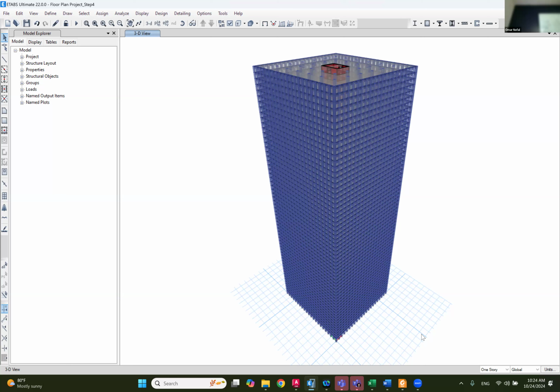You don't have to have shear walls everywhere. Inside the building you can use the space, because if you look at Burj Khalifa, walls are everywhere inside the building. Shear walls are almost cutting every space. But with this one, look at the spacing that we have inside. So you have a lot of space. It's not only economic in terms of cost, but the space inside is usable. Anyway, that's the building that we have. This building has gravity loads, I told you to assign this on the slab. So this building right now is ready to take the seismic load. Are we all clear on that?